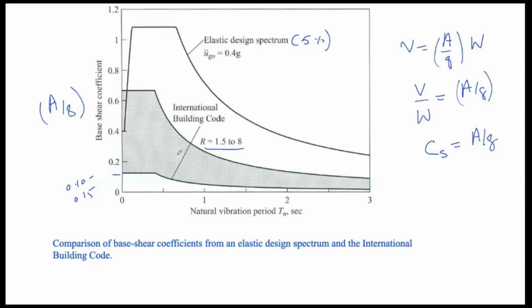The problem is that the structure would be damaged when subjected to ground motion that is represented by the design spectrum. For example, if you take any accelerogram matched to this design spectrum, through the spectrum compatibility or matching that we do, and you input that accelerogram to the structure, it will behave non-linearly, inelastically, and it will get damaged.